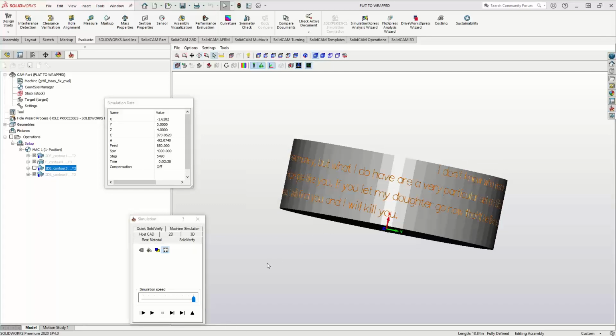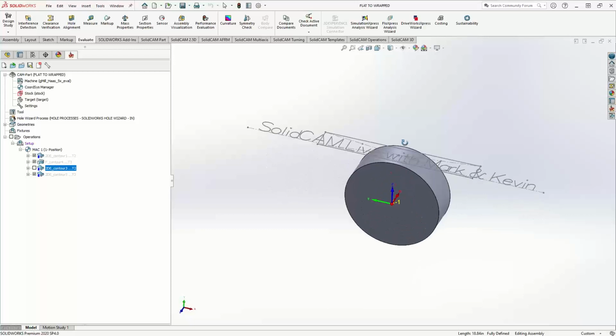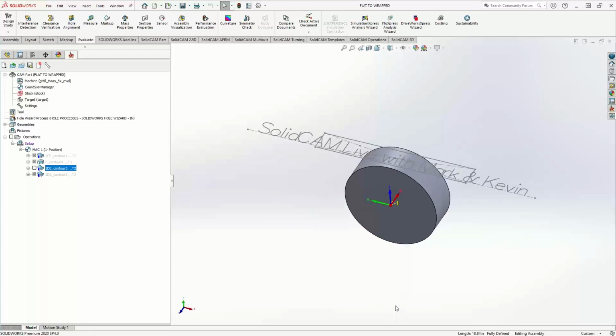Anyway, so that is engraving, but almost like helical engraving. The longer you make that thing, the more it'll just wrap itself around, and that's simply because I know how wide I want this to go. Now I centered it, but it doesn't necessarily have to be centered. All you have to remember with SolidWorks and SolidCAM is once you have something that's flat and you tell it to be wrapped using the 4th axis functionality, it'll just keep projecting whatever you have that's flat to the center. So that's why I was able to make that really long sketch.